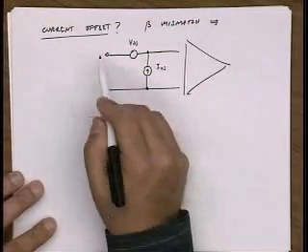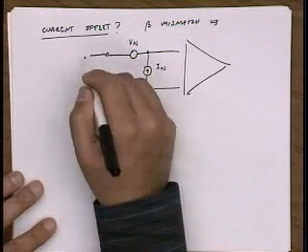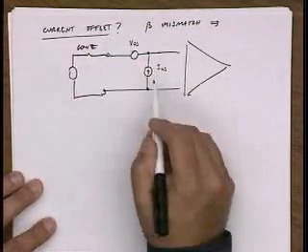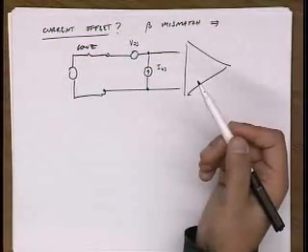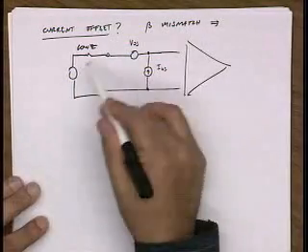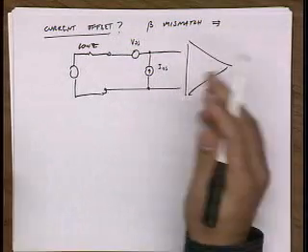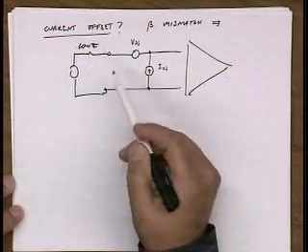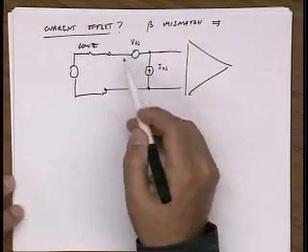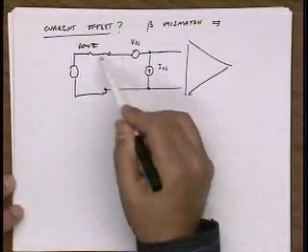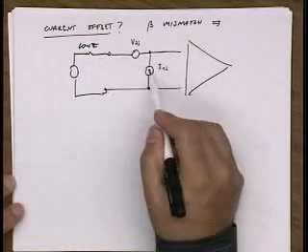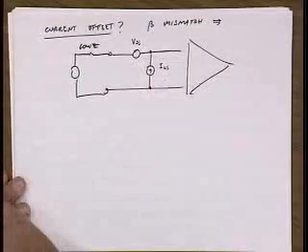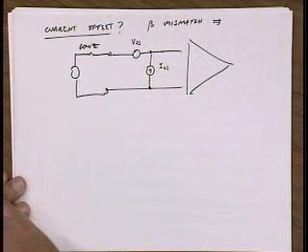And so if I voltage drive this thing, meaning I drive it with a low source impedance, then this offset current really doesn't matter, because it just gets shorted. It doesn't go into my amplifier. It's just like noise. We discussed noise. If I drive it with a high impedance, though, then the voltage doesn't matter because it's basically degenerated with a large resistor in series. And so then the offset current dominates. So depending on your application, you may care about offset current or voltage.